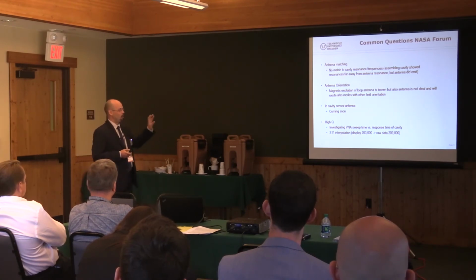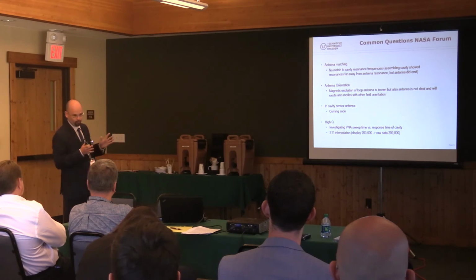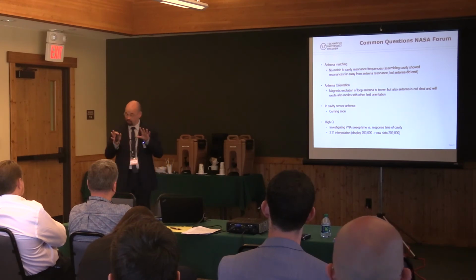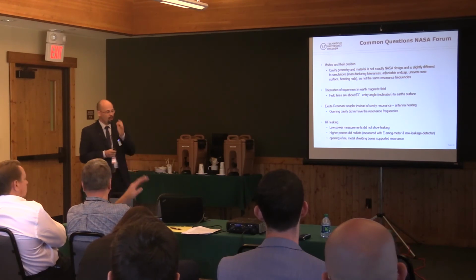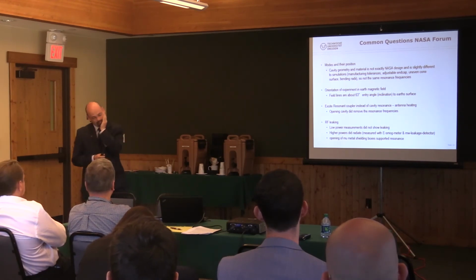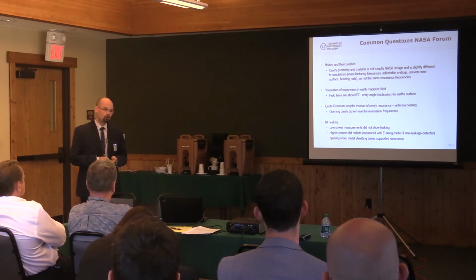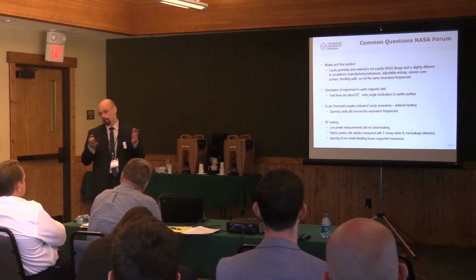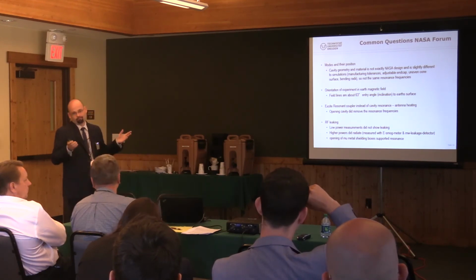I'm now investigating the problem of the sweep time of my VNA versus the response time of the cavity. Perhaps there's a problem of a too fast sweep for the power distribution inside of the cavity and the power reflection behavior. I still don't know. I'm just investigating this problem. How fast were you sweeping the VNA? Oh my God, I can't say. It's the standard setup for the device, and I just can't change it. I asked the manufacturer, and they just said, "Oh, you can do more averaging, you can do sweeps more often, but you can't change the sweep time itself." Yeah, I can't believe you'd see a problem, but I don't know what the sweep time is.